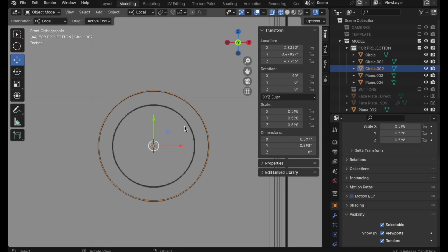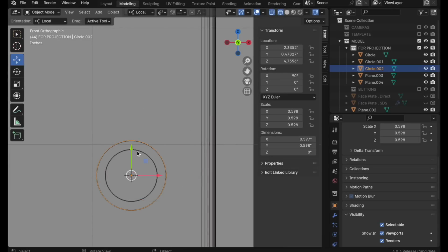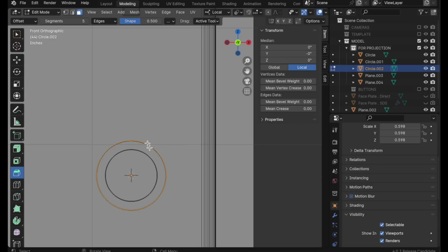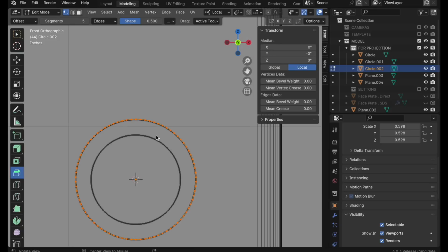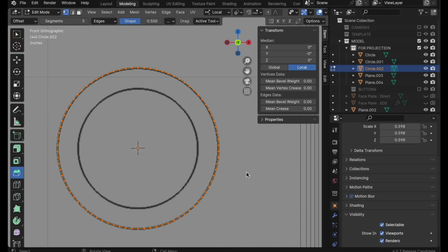So this is an inset area for an indicator. So let's come in and work on the dial. The dial is 270 degrees of cutout. Press the Tab key. Come into vertex mode where you can see those vertices. Press the F key to fill that.